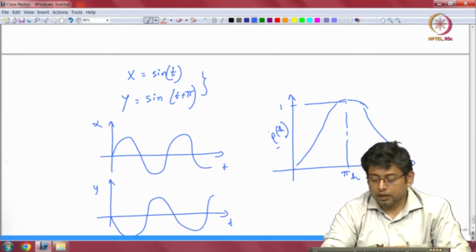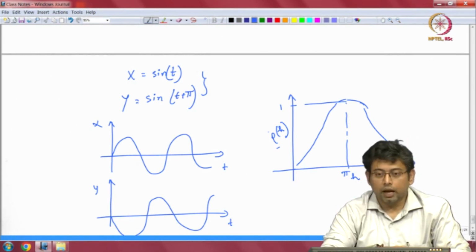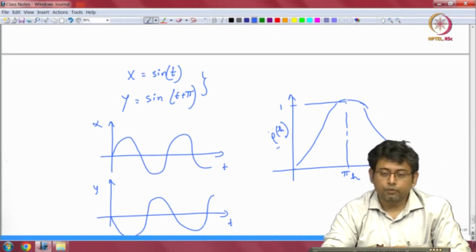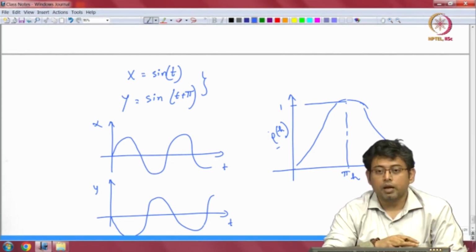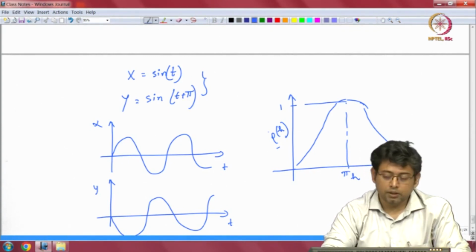This is an idea that we will use quite a bit when we do particle image velocimetry. We will have unknown displacements that we will try to back calculate by moving one image over the other, displacing it by various amounts, and seeing when the cross correlation function becomes a maximum. That way we will be able to get very accurate measurements of unknown displacements.